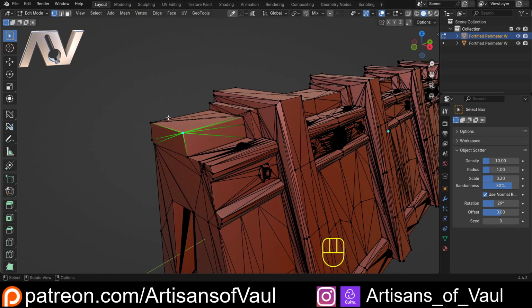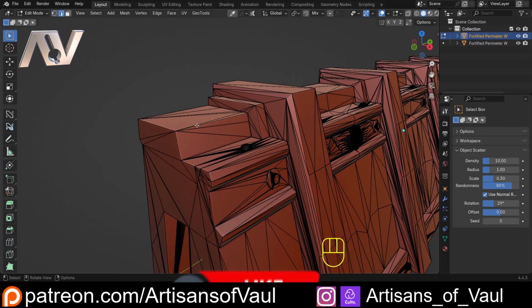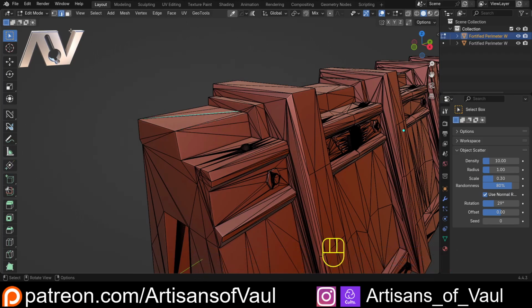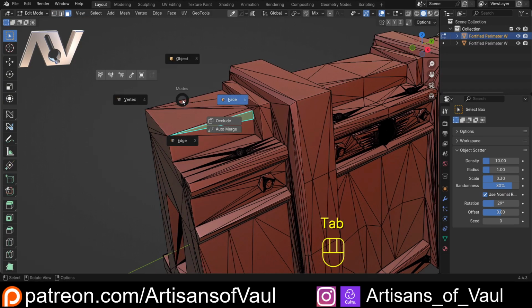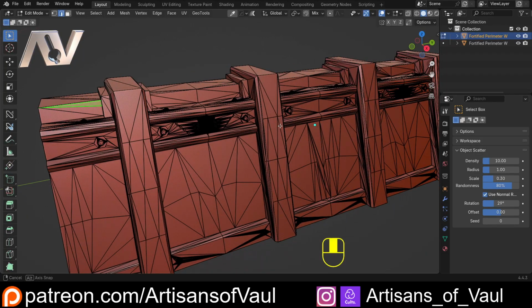For example, vertex mode, and you can just hit 1 to get in this, as well as coming up here, shows all the vertices, so that's all the points individually. The edges allow you to select all the edges, which are what connects two vertices together, and then face mode selects the faces. And you can get to that with 1, 2, and 3, or up in the corner, but I've got Machine Tools, and that gives you this pie menu, which should really clearly show you what I'm going to do. So I'm going to go to Edge mode, just for now,